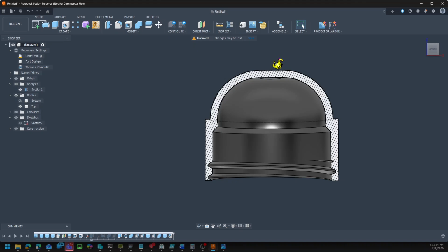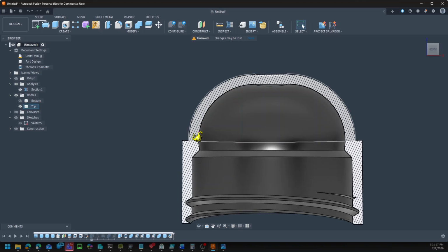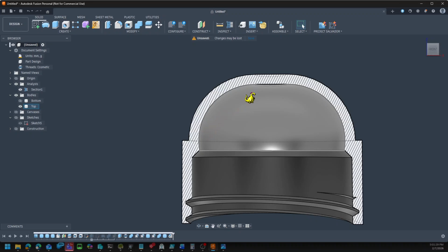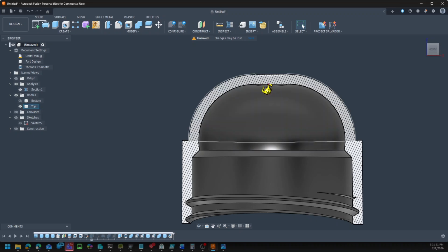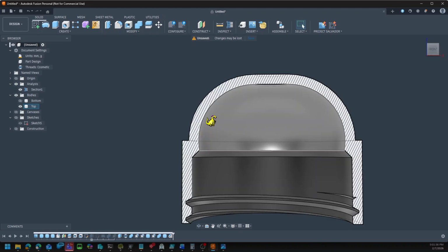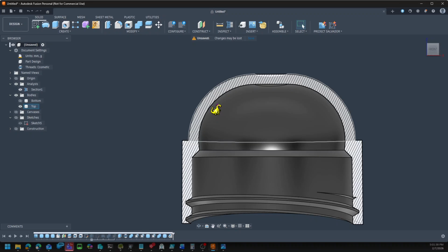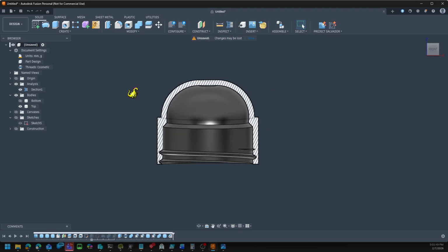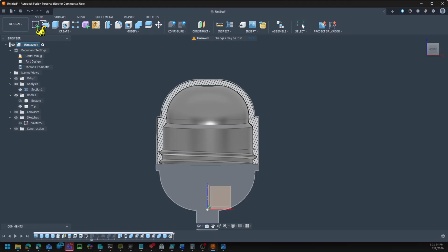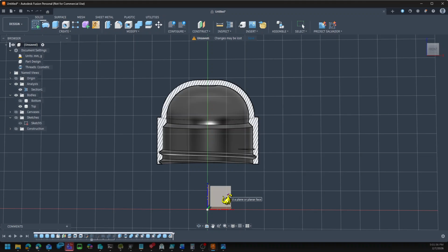Okay. The other part of this that's not 3D printable without support is here in the dome. So this face, or this angle, we're going to get up to about right here where the dinosaur's tail is, and then we're going to be printing a steeper overhang than the printer can print. I'm going to have to fix that to make it more printable. Lots of ways to do that. The way I'm going to do that is I'm going to create a sketch here on this face.